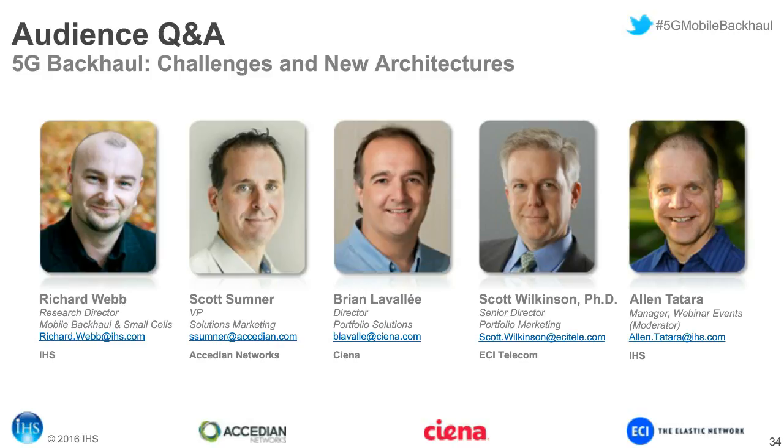Yeah, and I can just add a couple of points here, more down into the nuts and bolts. We talked to a lot of the MNOs around the world, and they're still deploying copper TDM-based backhaul services. So SDH, E3s, and so on. Stop doing that because that won't scale to 5G. If you're going to start deploying 5G with the very high data rates and multiple users at a given cell site, you probably don't want to do a microwave or millimeter wave backhaul. It won't scale.